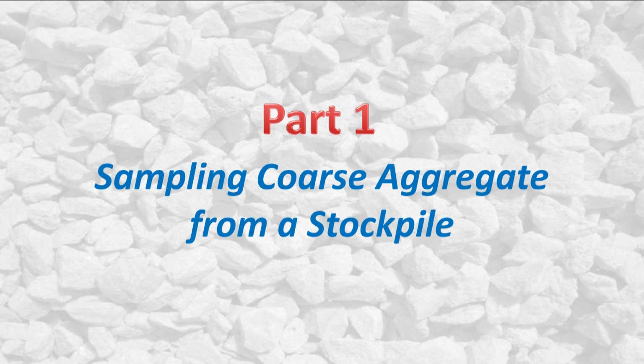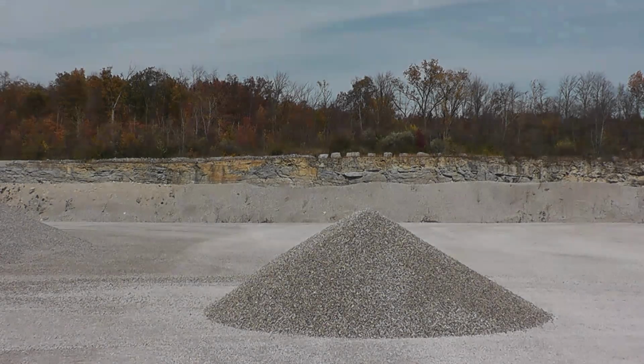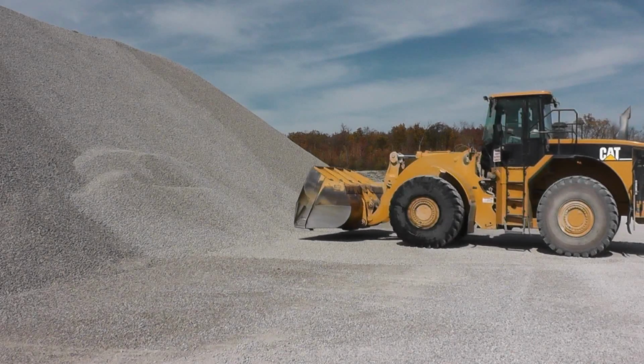Sampling coarse aggregates from a stockpile. The first step in the sampling procedure for coarse aggregates is to use a front-end loader to remove between 10 and 15 tons of material from the stockpile. This will become the sample pile. The loader operator uses the front-end loader to dig into the stockpile in the same manner in which he would if he were loading the truck for shipment.